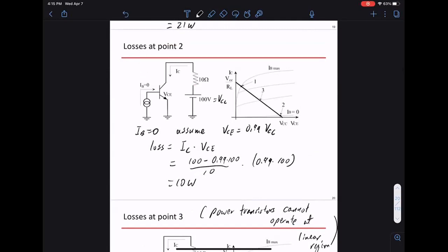But MOSFET is, in some sense, less robust. You have to be more careful about design. Whereas bipolar is just buy an off-the-shelf bipolar transistor. You can plug it into the circuit. As long as you avoid the saturation, avoid the linear region, it works.